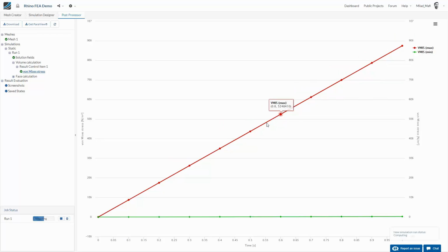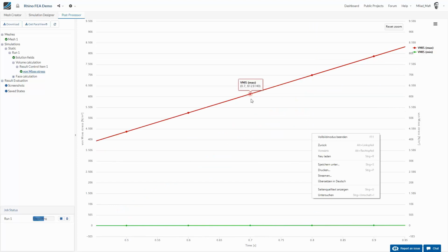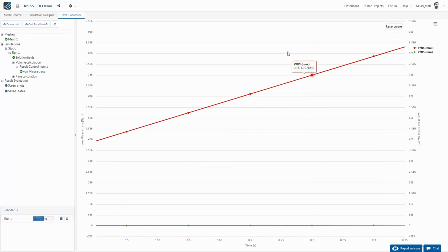And just to let you know, the yield strength, so the stress where plastic deformation will start, is around 60 megapascal, which is here. So until we have 70% of the load, everything is fine, but if it is higher, we will have plastic deformation inside this chair, which means that in the long term this chair will crack.